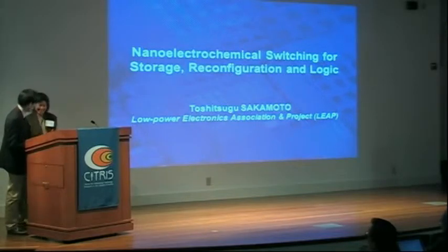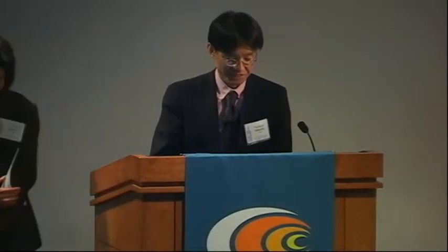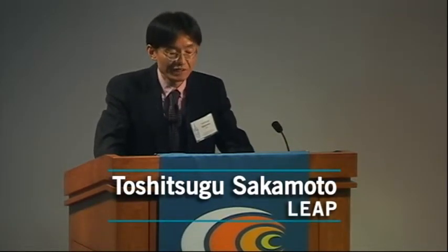Thank you for the kind introduction. Thank you very much. I'm from LEAP, which is one of the projects of TIA, Tsukuba Innovation Arena. This was explained by Dr. Yokoyama. So today I'm going to give a talk about the non-volatile switch using the electrochemical reaction, which we call atom switch. And Professor Philip Wong gave us a nice introduction. Our memory is categorized as CBRAM, conducting bridge RAM.